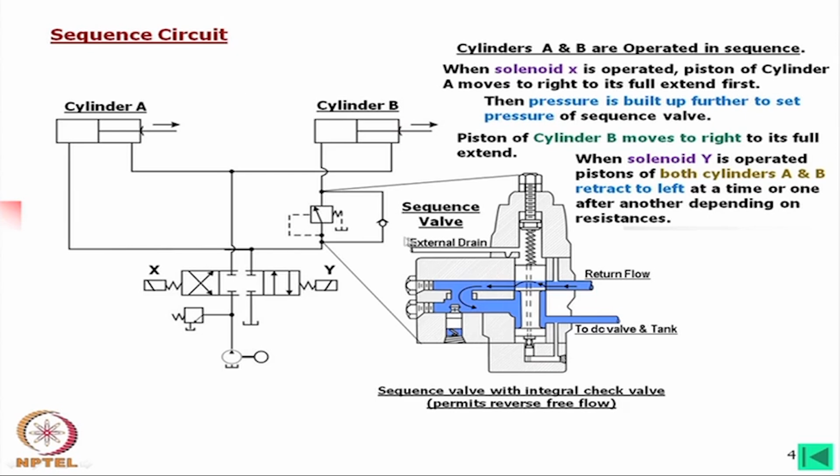This is not very understandable in comparison to this, but actually for operating cylinder B, this spool has to open and then oil will go like this, and the path shown is the return path. In case of this forward flow to cylinder B, this will be opened, which also can be actuated by a remote control.